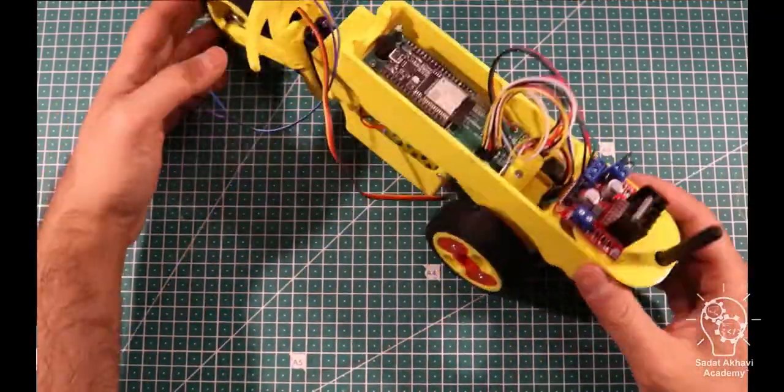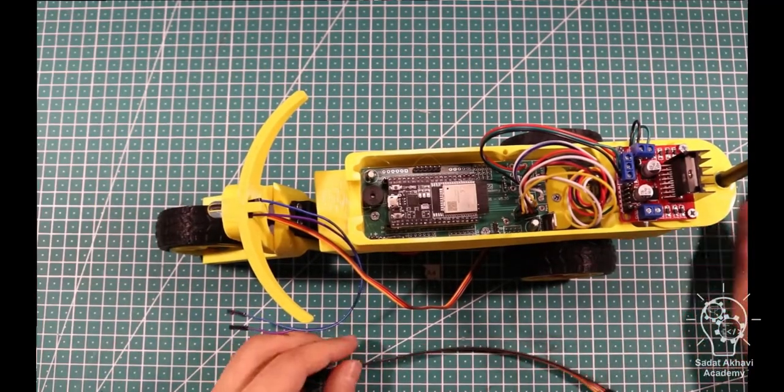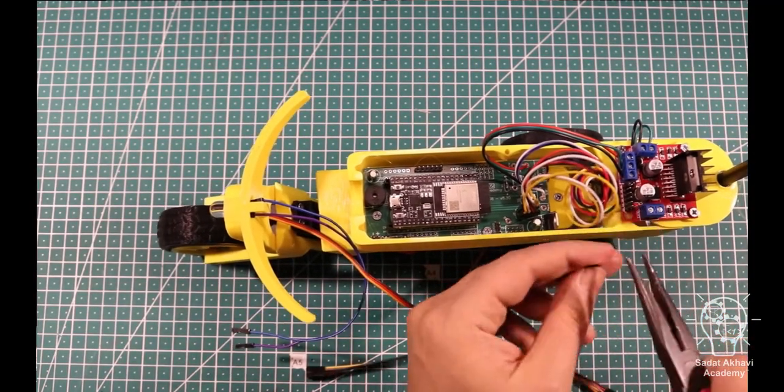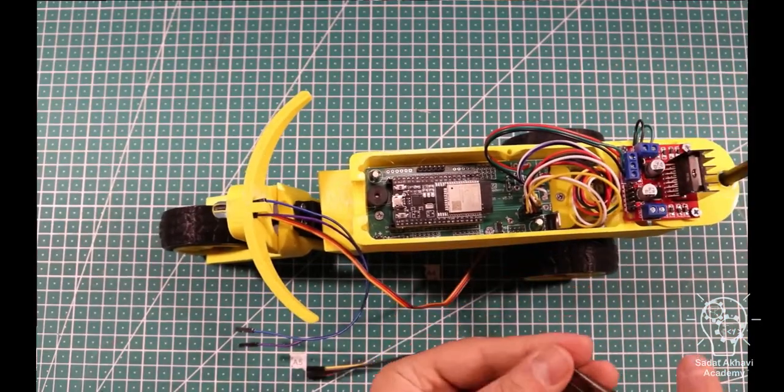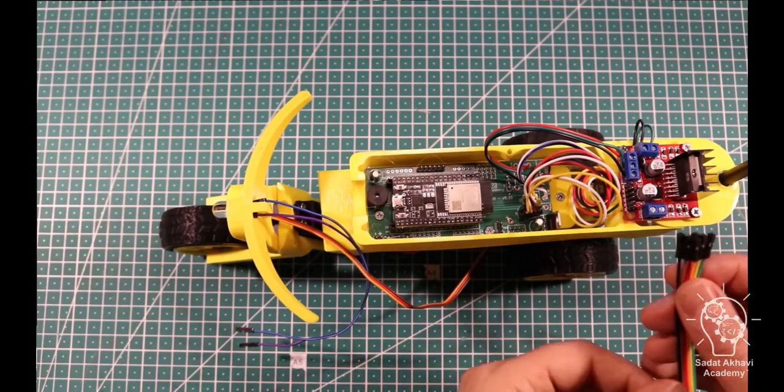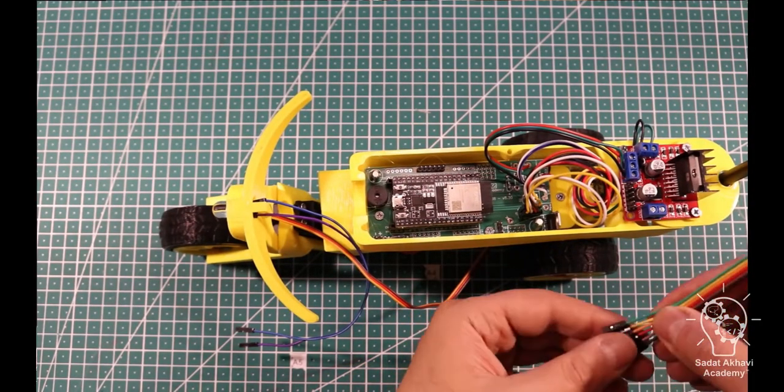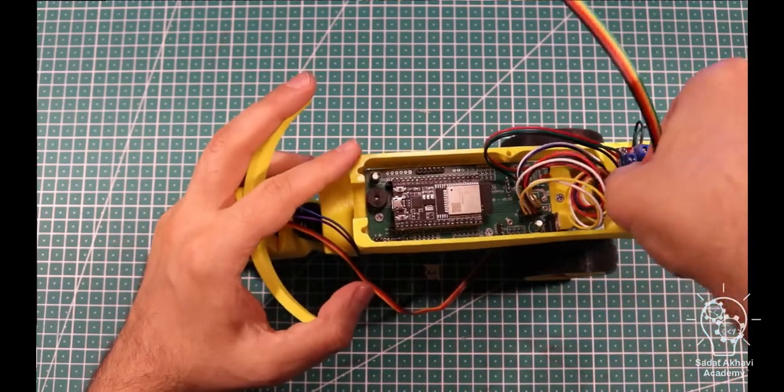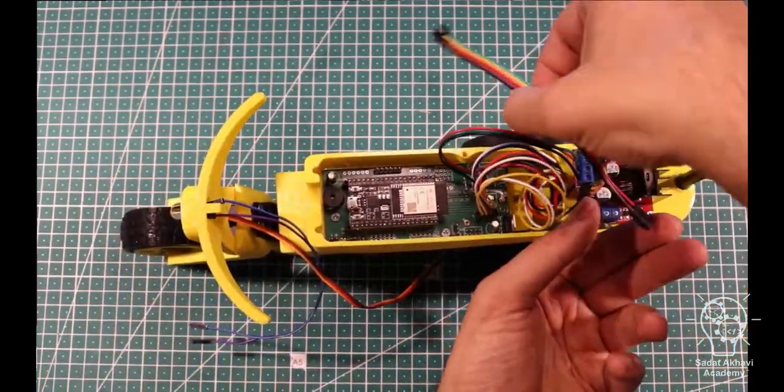Connect the 6 data pins of the module to the controller PCB. If there is a jumper on these connectors, it is safe to remove them as they are unnecessary. Follow the assembly document for wiring.